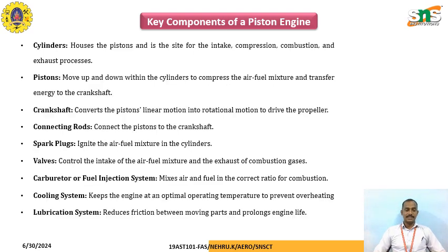Key components: cylinder, piston, crankshaft, connecting rod, spark plug, valves, carburetor, fuel injection system, cooling system, lubrication system. Crankshaft, piston, cylinder that we know. Connecting rod connects the piston and the crankshaft. Spark plug ignites the fuel-air mixture in the cylinder.